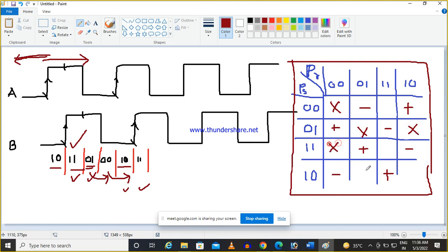Sir, here what is the variable that is incremented or decremented? I will define one variable like x in the code. It will count the number of pulses. So if I know the pulse per revolution, that is called PPR, then I can find out how many pulses I can receive. Say pulse per revolution is n.